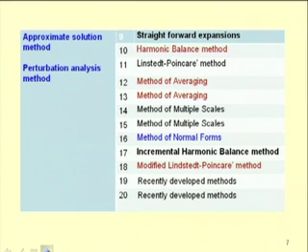So, then we will go for perturbation analysis, where I will tell you about the Lindstedt-Poincare method, method of averaging, method of multiple scales, method of normal forms, incremental harmonic balance method, modified Lindstedt-Poincare method and several recently developed methods. So, after deriving this equation and by using these analytical or perturbation methods, we will convert our ordinary second order differential equation of motion to a set of first order differential equations. For steady state solution, we can find a set of algebraic equations, which we can numerically solve to find the response of the system.